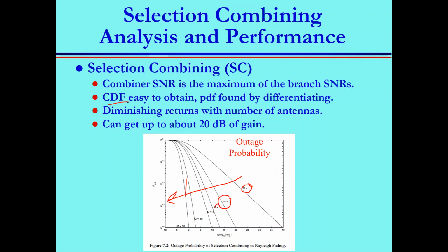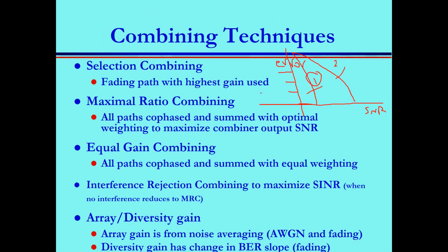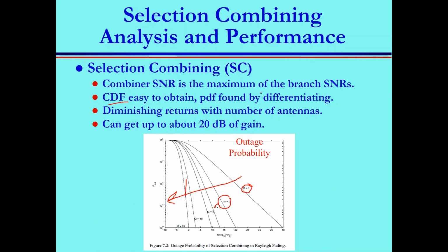the point here in wireless is that it's not only visualization and concepts; we also want to analyze the performance. I want you to mathematically tell me what the bit error rate would be and how to calculate it. To do that, you need to find the statistics of each received symbol from each antenna and then find the statistics of the sum.